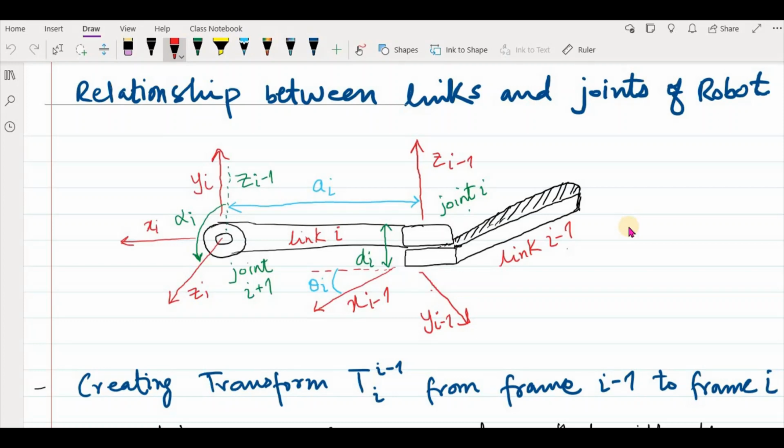So that's what we are doing. Previously, you remember we were doing it using transformation matrices, which were more generalized, and they had a portion of rotation and then a vector for translation, and you just multiply these transformation matrices and you get the final answer. But in the DH notation, we are using a specified method where we want to focus more on your Z and X frames, and there are some other parameters that are important.